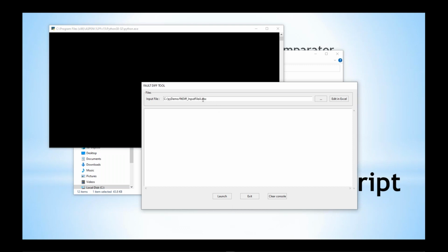Python is reading in that Excel. It will read all the data in Excel and follow that instruction, which is to load that OneLiner network, perform all the fault simulation, and write out the result for that relay group and that relay. So I'm launching that action now.